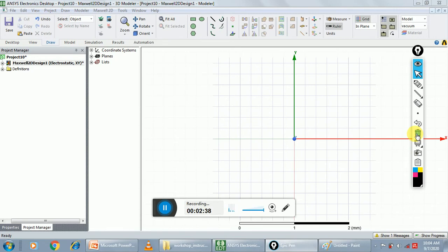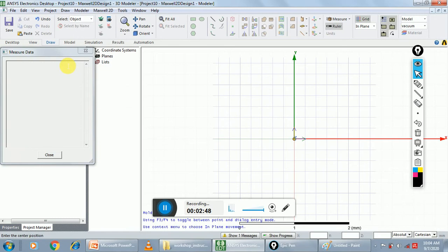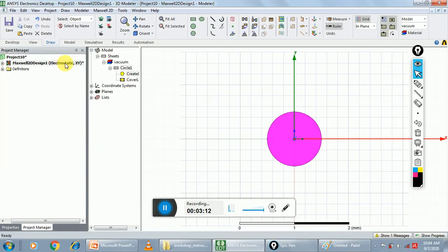Okay, first start with inner. Here we create inner with the help of a circle. Go to draw and select circle. Put the dimensions of the circle: first select the coordinate, so x0, y0 and z is 0, make it OK, and dx is 0.5, and dy by default 0, dz 0, make it OK. This is your circle 1.